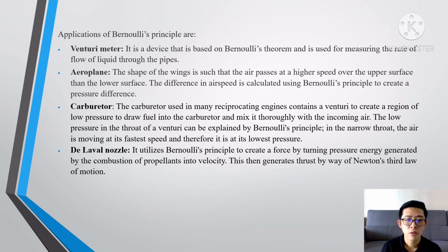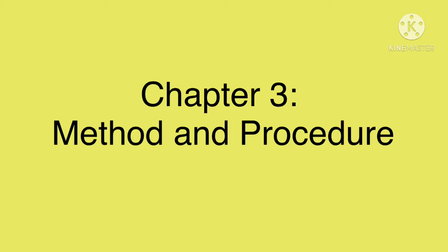The Laval nozzle utilizes Bernoulli's principle to create a force by turning pressure energy generated by the combustion of propellants into velocity. This then generates thrust by way of Newton's third law of motion.